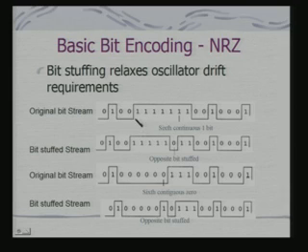If you look into the structure, say this is your original bit stream. If there are two zeros, there are no transitions in between, so they are at a constant voltage level. I am looking at 0 as low voltage, and then there is a continuous run of 6 ones, so it is a continuous voltage level. Since there are no transitions during the bit interval, this is non-return to 0. Obviously, what it requires is that there cannot be a clock drift from processing element to processing element. If there is a clock drift, then the interpretation of these bit intervals can become erroneous. So, instead of counting 6 ones, I may count 5 ones, and then there will be wrong data.